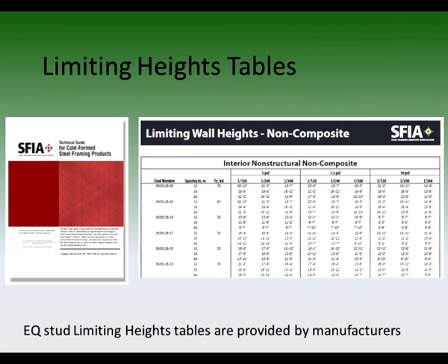For EQ studs, the manufacturer of the product must supply the limiting heights tables for each product they produce. Although this isn't a seminar on stud selection, we will review briefly some limiting heights examples so you understand how it's applied and that there is not much difference in using tables between a conventional and EQ product.